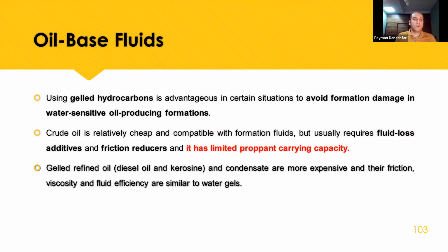And as I told before, it is advantageous in certain situations to avoid formation damage in water-sensitive oil-producing formations. And crude oil is relatively cheap and compatible with formation fluid for oil and gas wells, but it usually requires a fluid-loss additive and friction reducer, and it has limited proppant carrying capacity. It's important for us. Proppant carrying capacity is important for us.